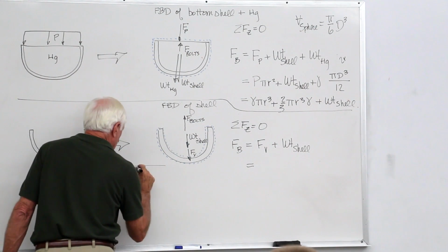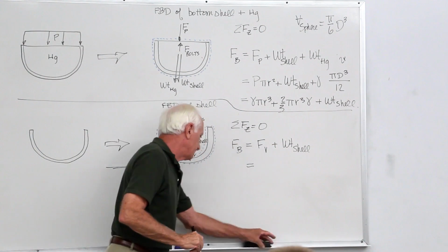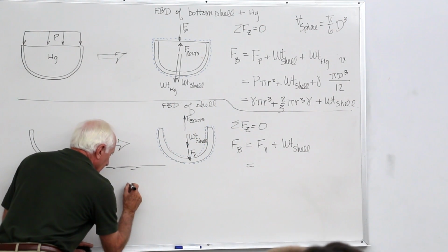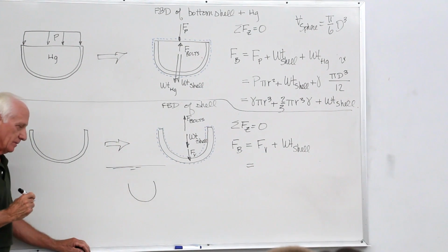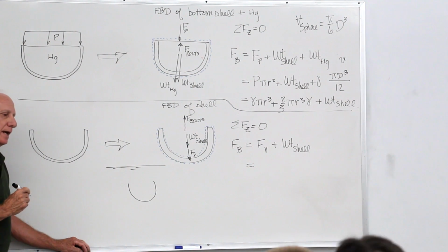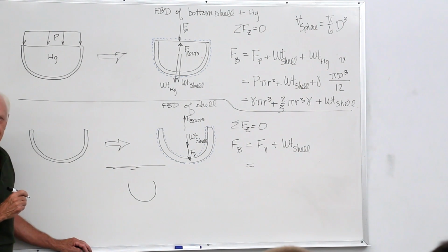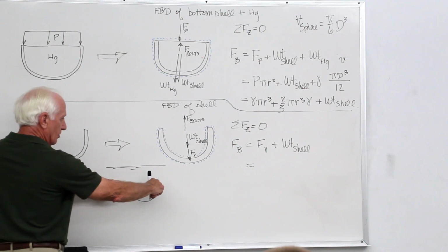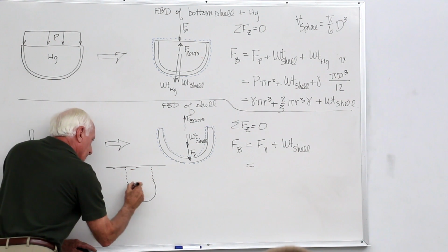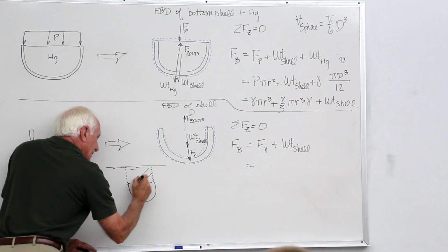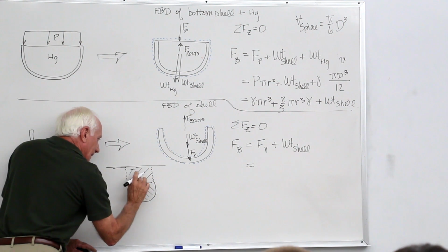So here's the free surface of the mercury. Here's the curved surface of the mercury. Okay, what's the vertical force on that curved surface? It's gamma times the volume of the fluid above the curved surface extending to the free surface, real or imaginary. Take your fingers on both ends. Go straight up. Stop. That's the volume. What is that volume? That volume plus that volume. That's the volume.